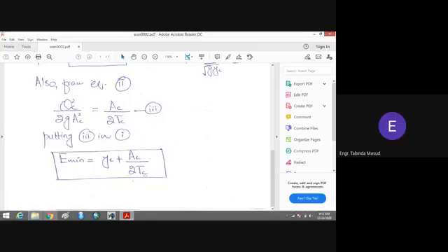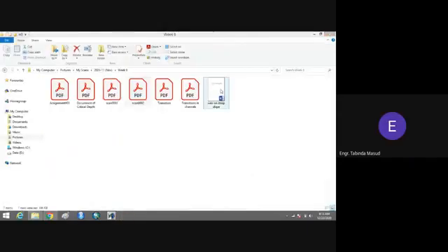If you remember, for rectangular channels we developed an equation that minimum specific energy is equal to 3 by 2 into critical depth of the flow. But here the equation looks different. If you modify this equation for the rectangular channel, putting the area of the rectangle and the top width of the rectangular channel, that is equal to B, you will see that the equation becomes E minimum is equal to 3 by 2 into critical depth of the flow. So this was the generalized form of equations which you can use for any kind of channel for the critical condition only.